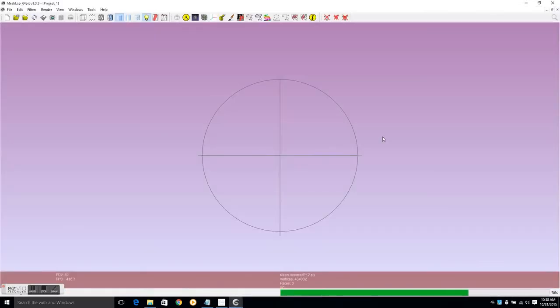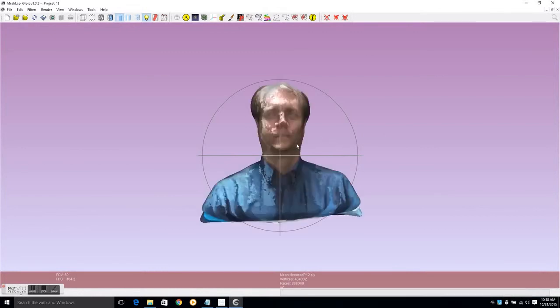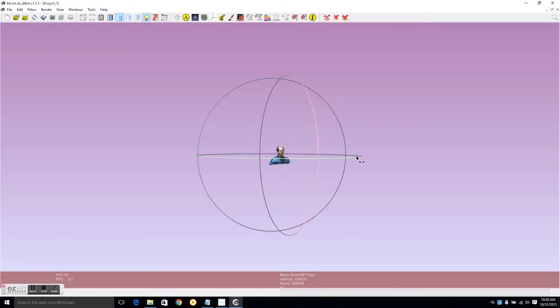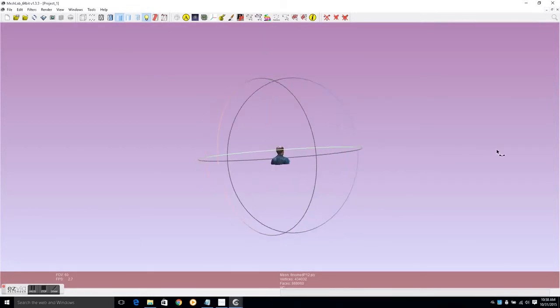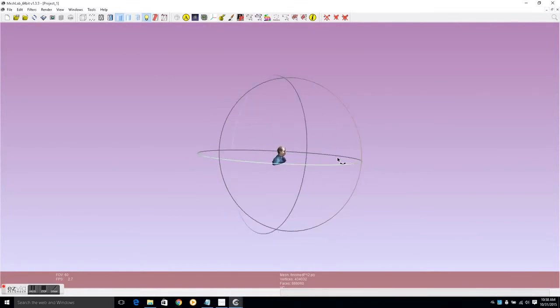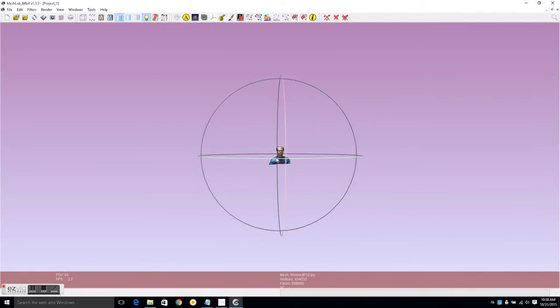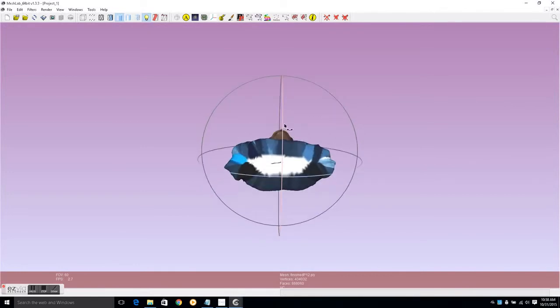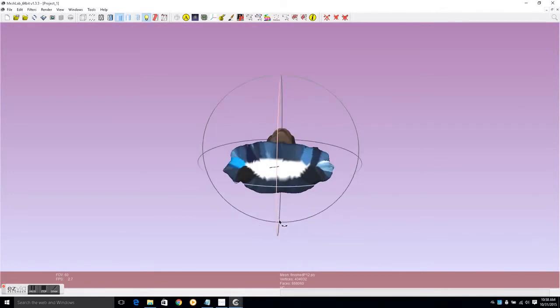And there you could see, if you double clicked on the project name at the top, it'll open the project folder, and under the completed folder will be the mesh you resized. It'll have the mesh name, but then it'll add a number at the end depending which size you chose. If you chose 1/12, it'll add a 12. If you chose 1/6, it'll add a 6 at the end.